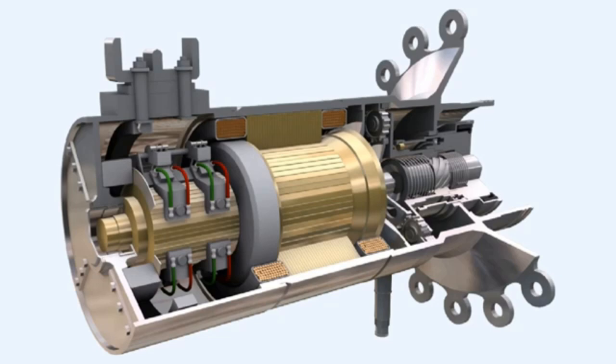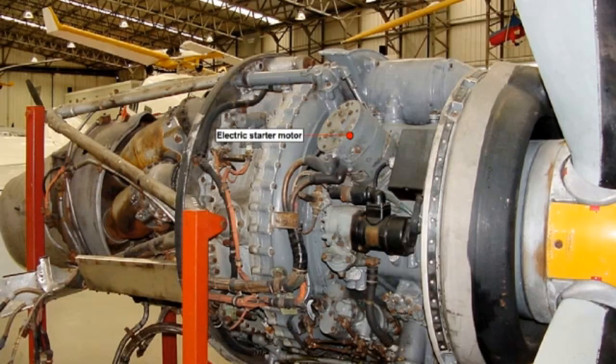The electric starter motor was the original means of starting a gas turbine engine, and is still used in smaller executive jets and helicopters. However, it's fallen out of favour in larger and more modern engines because of its weight. This picture shows a Dart engine where the electric starter motor is fixed in front of the compressor casing. The electric starter motor can, however, be attached to the engine accessory gearbox. In the latter circumstance, the starter drives the compressor through the gearbox.